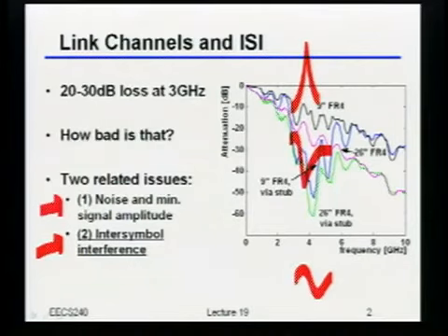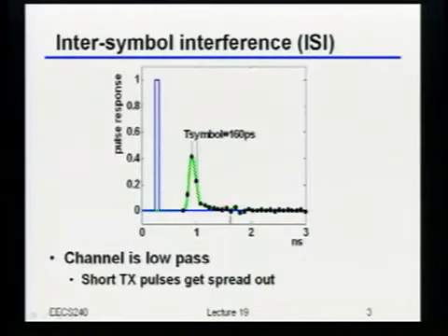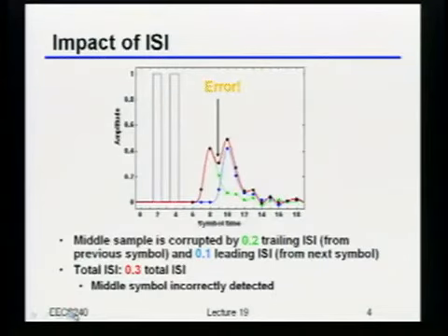So you tend to see these ripply things when you have either notches or peaks in the transfer function. Indeed, this little junk that's happening over here is just reflections off of various discontinuities in the system. Now, let's see why we should care about this.